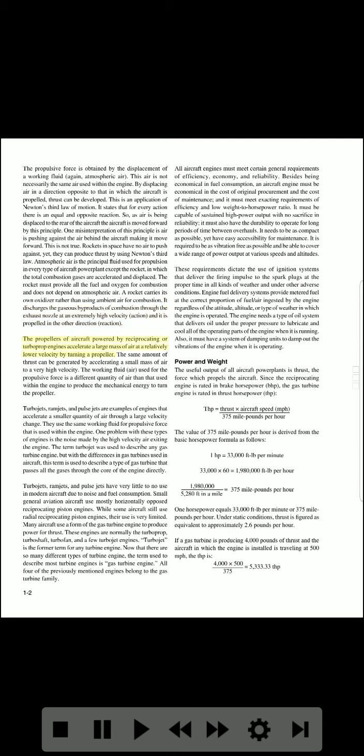The propellers of aircraft powered by reciprocating or turboprop engines accelerate a large mass of air at a relatively lower velocity by turning a propeller. The same amount of thrust can be generated by accelerating a small mass of air to a very high velocity. The working fluid, air, used for the propulsive force is a different quantity of air than that used within the engine to produce the mechanical energy to turn the propeller.